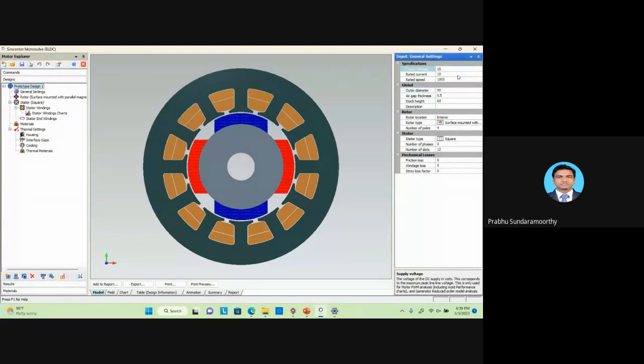So now we need to set our voltage, right? To set our voltage, we should know the basic criteria of what is available in the market. The batteries available in the market are 12 volt, right? So in multiples of 12 only, we need to assign the batteries. I am going for 60 volt. So 12 plus 12, another 12, again another 12. We will go for either 48 or 60. So five batteries I am going to arrange, and I am going to get 60 volt, right?